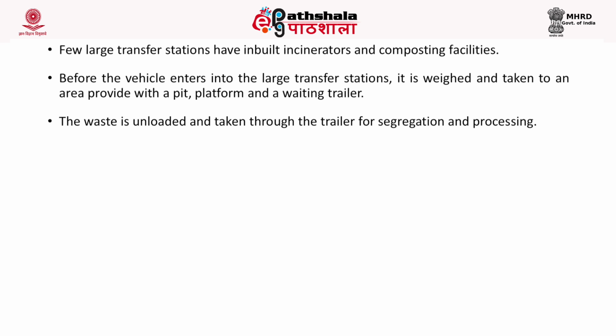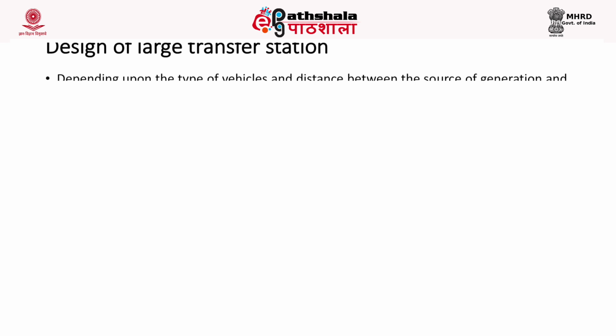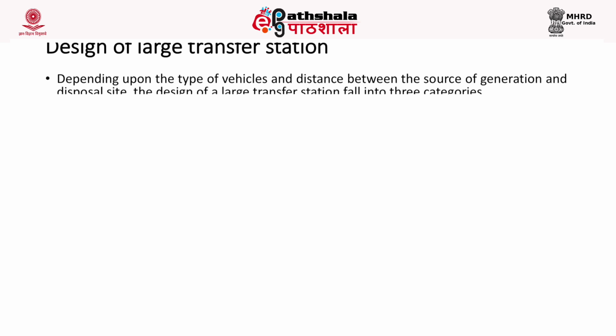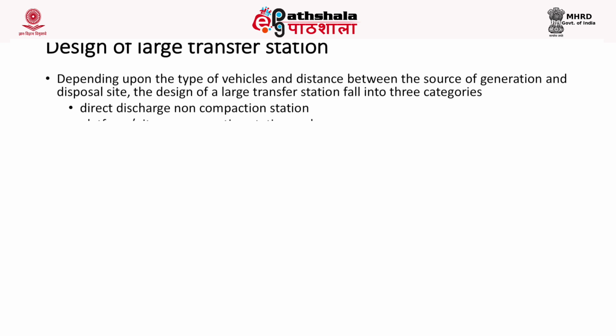Now, before the vehicle enters and leaves the transfer station, it will be weighed, and the waste will be taken along with the truck to an area where it will have a pit, platform and a waiting trailer. The waste is unloaded and then through the trailer it is taken for segregation and processing. Now, we will look into the design of a large transfer station.